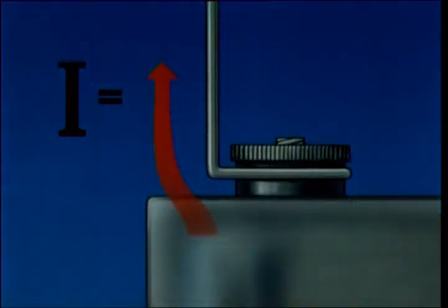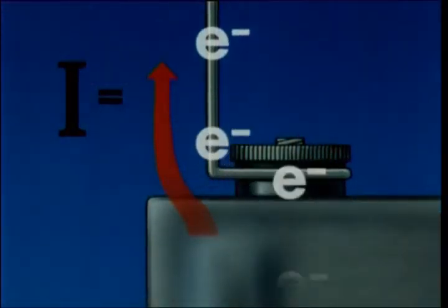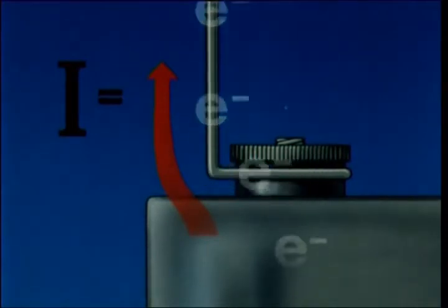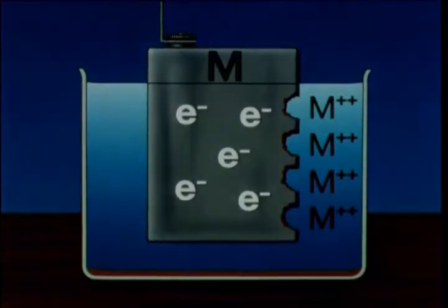The electrons accumulate in the metal, the potential goes negative, and the positive ions find it more difficult to escape, and the process stops. If some of the electrons are allowed to flow away, the metal becomes more positive. The positive metal ions escape more easily, and corrosion continues.